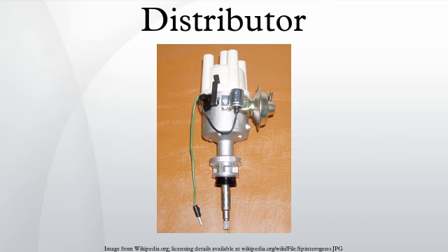More recent layouts utilize a coil located very near to or directly on top of each spark plug. This design avoids the need to transmit very high voltages, which is often a source of trouble, especially in damp conditions. Both direct and remote distributorless systems also allow finer levels of ignition control by the engine computer, which helps to increase power output, decrease fuel consumption and emissions, and implement features such as active fuel management.